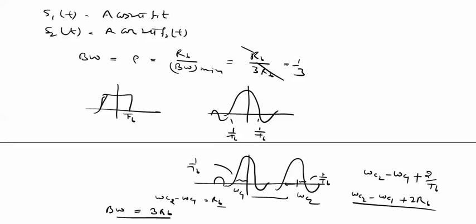In the FSK scheme, we are transmitting two different types of frequency alternately. Those frequencies are integral multiples of 1 upon TB and their difference is also 1 upon TB.